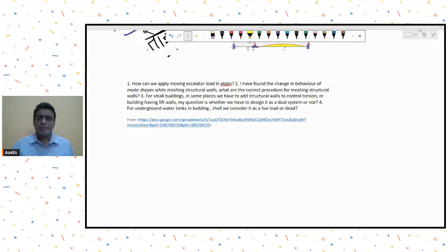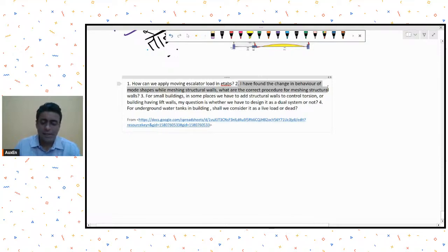But anyway, it's a simple data sheet, just point loads given and where to apply them is given to us. So you really don't need to apply any moving load. Simple answer: just apply the loads as given. The escalator company will take the necessary dynamic impact factors and give you the loads, which you will apply as simple static point loads.